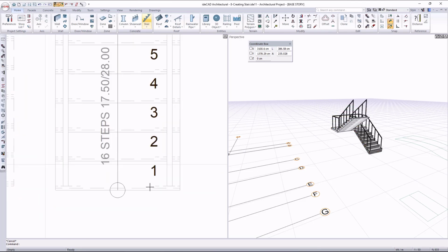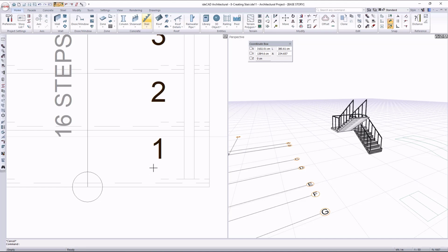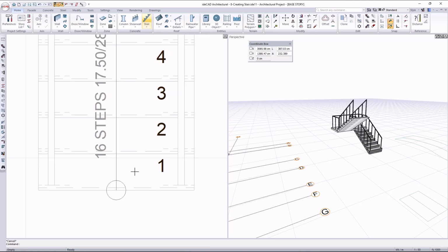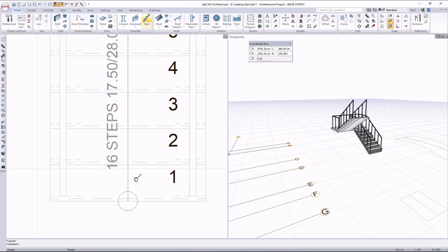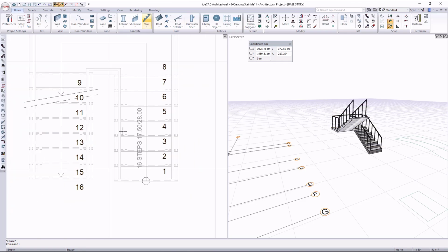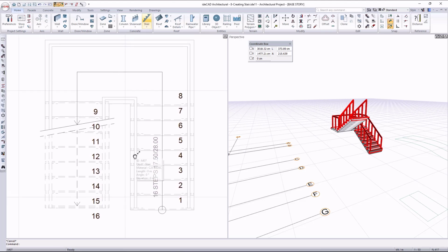There are 3 different lines in the stair area. The innermost dashed line represents the concrete structure of the stair. The middle dashed line represents the riser covering. The outermost solid line represents the stair nosing, the protruding front edge of the tread. Since the concrete and riser coverings are below the stair surface, they are shown as dashed lines in the drawing. The line representing the nosing is considered the visible edge of the stair and is drawn as a solid line.